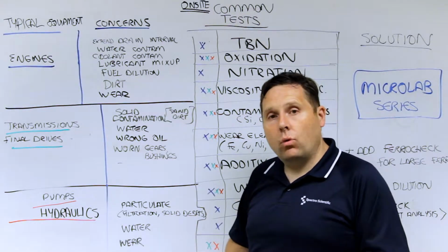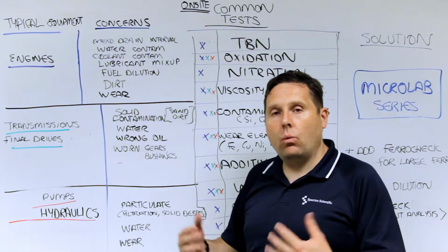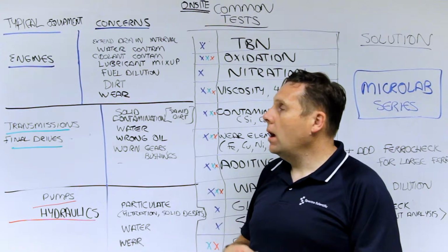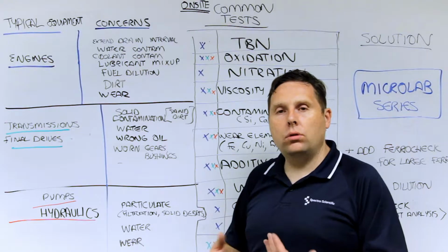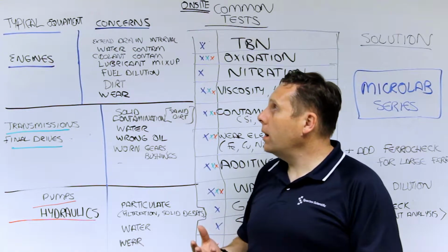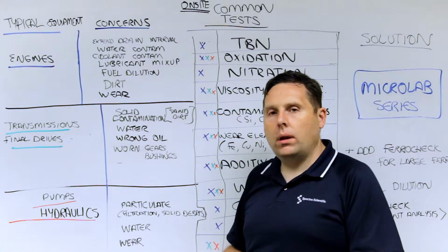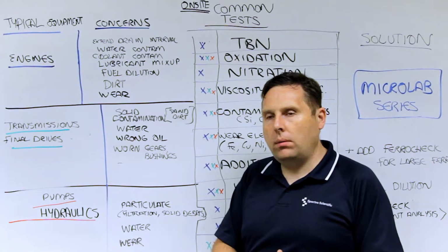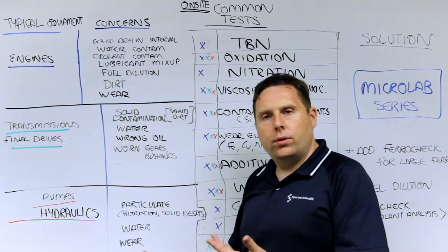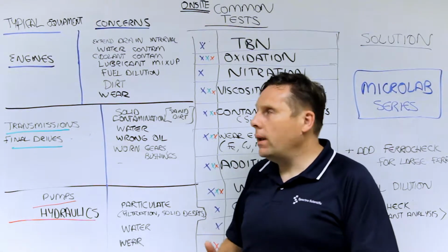You want to check if there's water contamination. It's quite common. If you get water into the engine, it's going to have problems. Coolant contamination as a result of coolant leaks, things like that. Lubricant mix-up. We may have put the wrong oil in by accident, or we thought we were putting in brand X when we should have been putting in brand Y. We put a transmission oil into an engine oil, stuff like that.